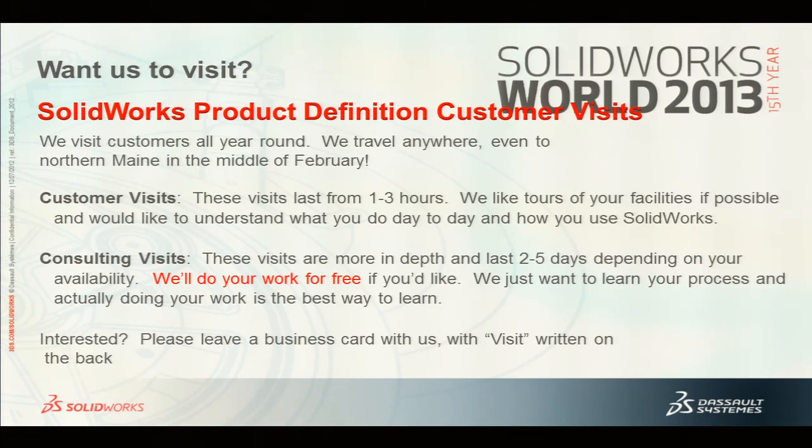Questions? Any other questions? Yes. With your NextEngine, are you sticking with the core software it came with, or are you using the add-on software? I'm using the core software, just ScanStudio. The ScanStudio that comes with NextEngine does all the alignment and meshing and taking it to SolidWorks. Now, NextEngine for the last couple of years has bundled RapidWorks with it, and you're free to use that too. RapidWorks is basically a duplication of what I showed with Scan to 3D, and maybe a little more.